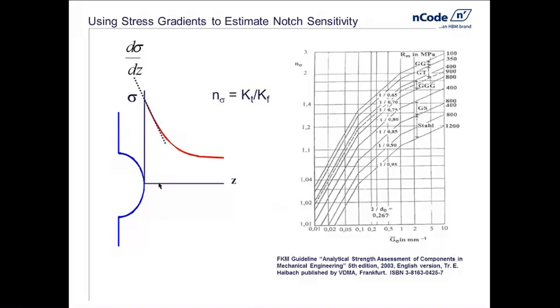And with that information and material information, and again, we've built the material information into DesignLife, it was obtained from a fatigue design guide, the FKM design guide out of Germany. And these curves on the right-hand side represent the fatigue performance of different grades of steel, or actually grades of materials here. We have steel, and cast irons at different UTS values.